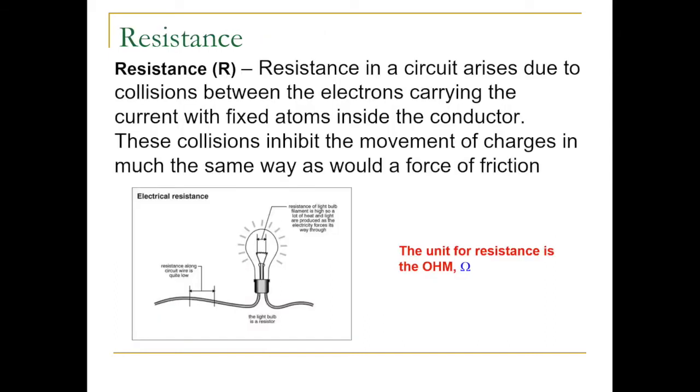So now we can talk about the last quantity that plays a key role in circuits, and it's this idea of resistance. And we've all heard of resistance before. Well, physically, the definition is that there are these collisions that are taking place inside an electronic device. And the electrons that are coming into this device are colliding with the actual conduction material, and the result is there is this energy loss due to these collisions in the form of thermal energy. If you've ever put your hand over a resistor or touched a resistor, you'll notice that they're exceptionally hot. And it is because of this use of energy that's so important.